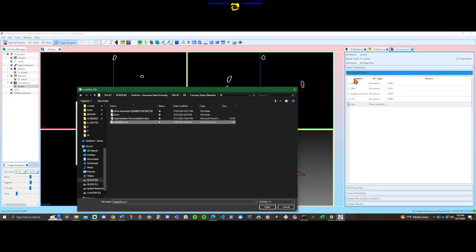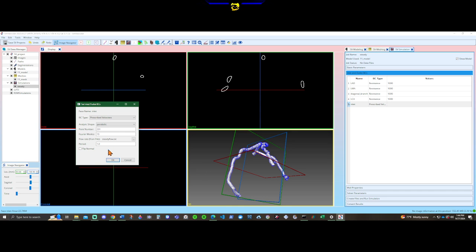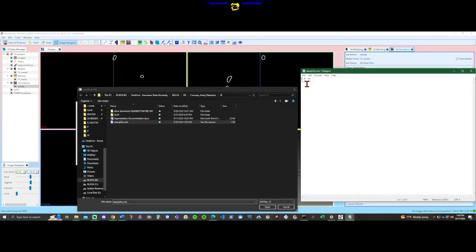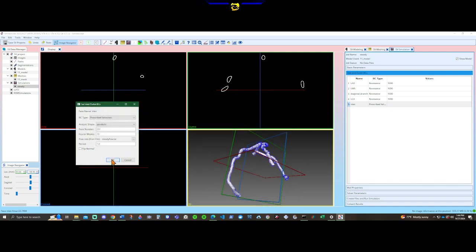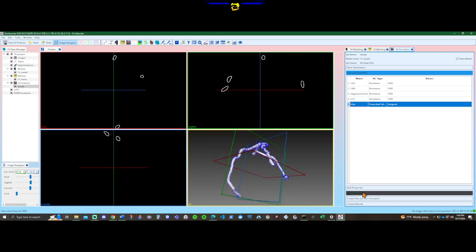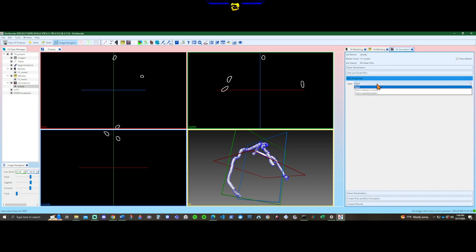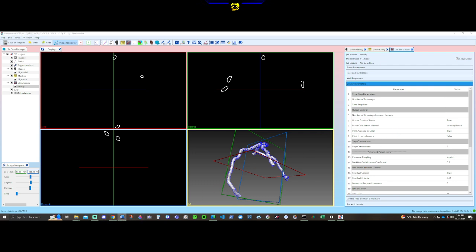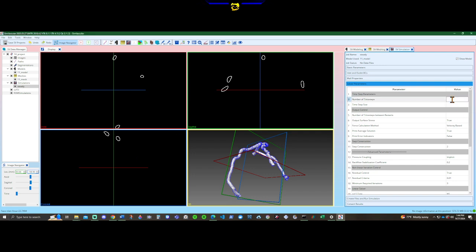It doesn't matter where this file is, but click it, open it. Make sure you have those values right there. Again, 0, -65, 1, -65, like that. Click OK. Then move on to the next section. Keep this as rigid. Then for solver parameters, I'm going to go through this pretty quickly. So feel free to go back and keep the values that I use.